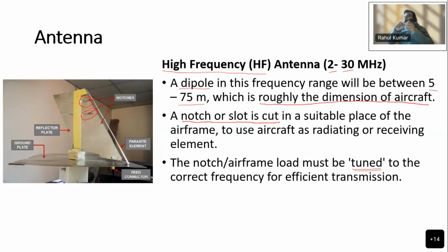It's not like you cut a notch anywhere in the fuselage or of any length. It should be of a specific length and designed properly, with specific length, depth, and so on. That is your tuning. So these notches should be tuned to the correct frequency for efficient transmission.